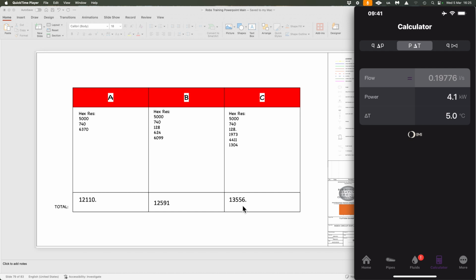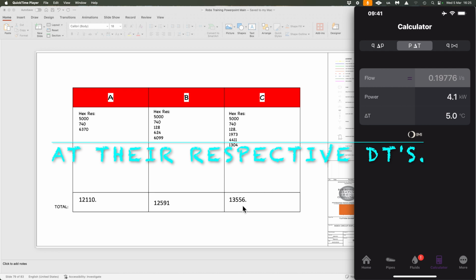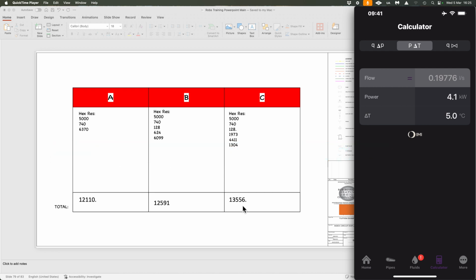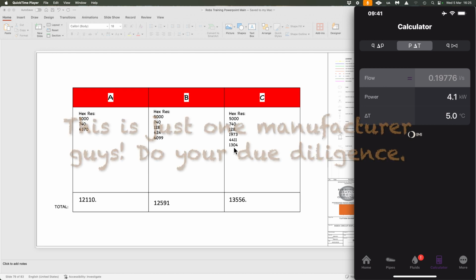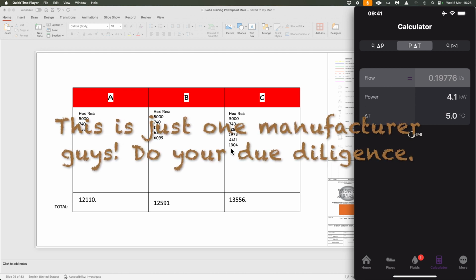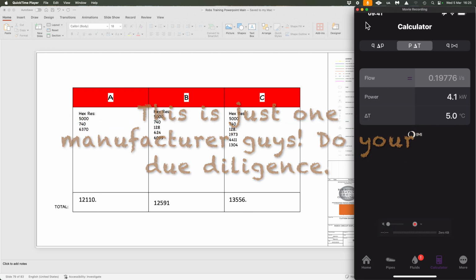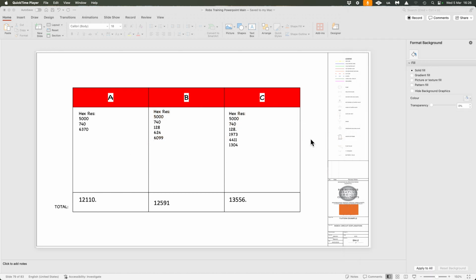So you need to find out what the kPa rating is of any motorized valves that are within the system, any radiator valves that are in the system that you have. And I'm just going to do a quick demo here looking at this. So if we take that last radiator there, which was the last section of pipework going to the last radiator, let me just push that down a second and I'll show you what I mean.